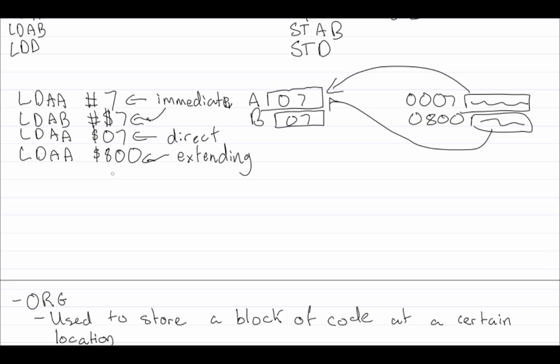Since here we have 4 digits, we're taking up the full 16 bits. We've given the instruction a 16-bit address. This is the reason why it's an extended direct addressing mode. Now this stuff becomes important because we need to be able to convert this into machine code.